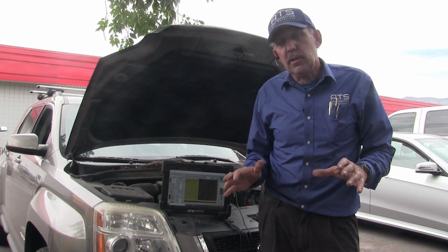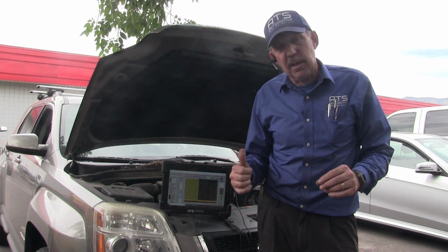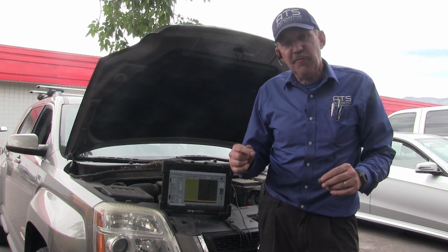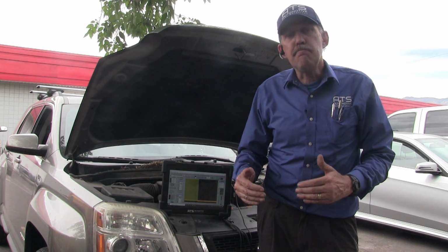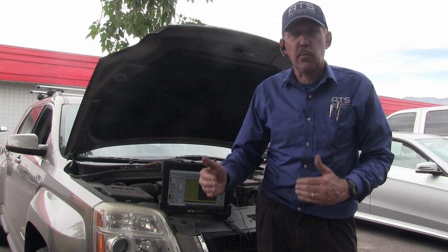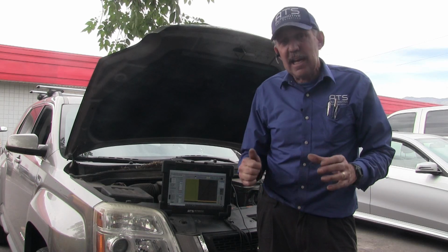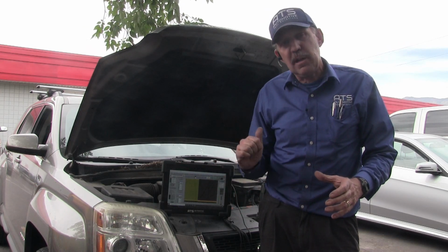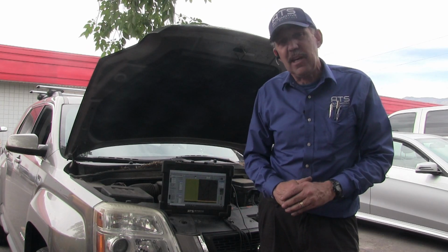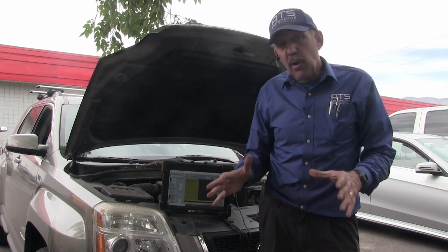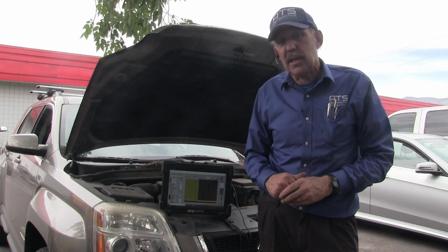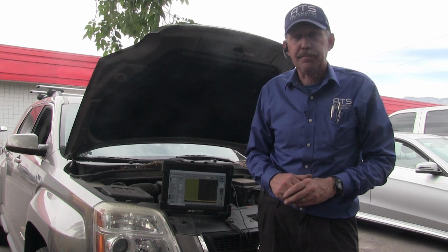So what we want to do is take a gas analyzer, put it in the tailpipe, and if the fuel control system's movement or the fuel trim was correct, I'll have stoich, I'll have a lambda of 1. If it's incorrect, then that shows me that I have some type of problem in the feedback system. So before we unplug anything, let's do one more test. Let's get the 5 gas.